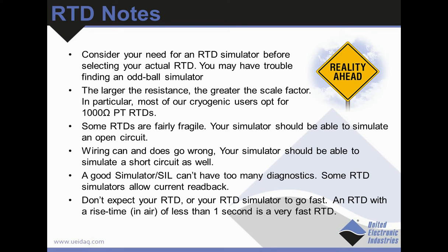Whereas if you design some fairly simple diagnostics into these boards, it becomes very easy to figure out what wire broke or what wire shorted. So a good simulator or SIL can't have too much diagnostics. They work fine forever, but they're very complicated machines, and when something does break, it can take a long time to find out what happened unless you've built in the diagnostics.